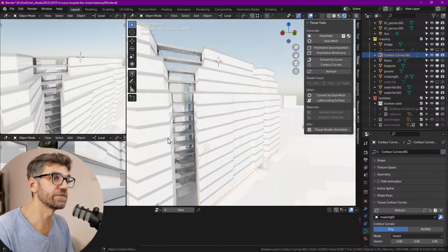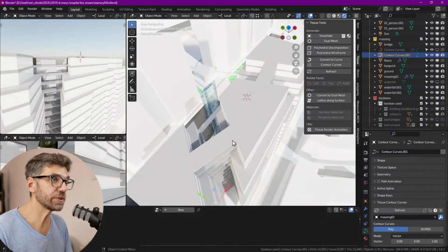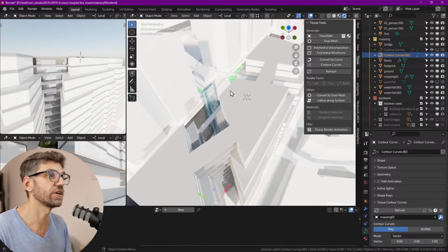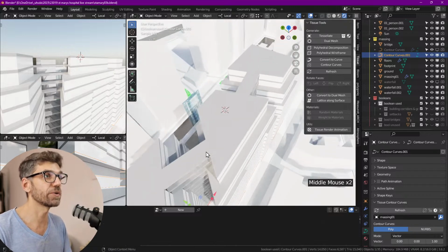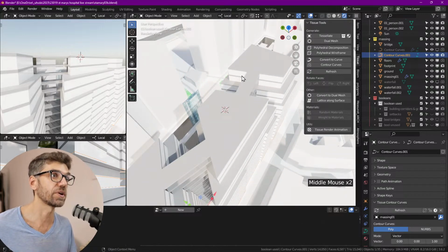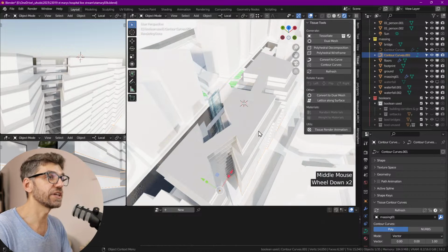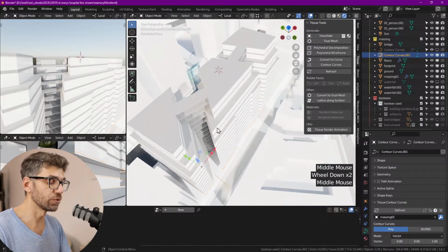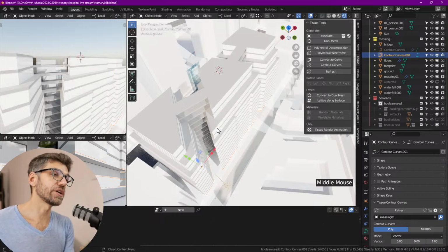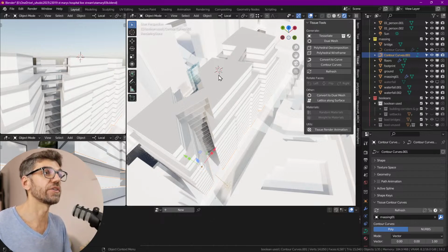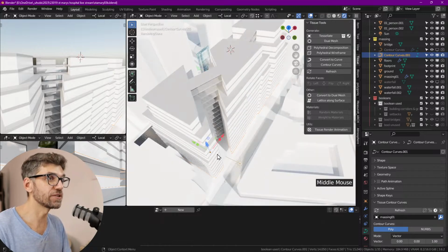Now, why do we need the bridges in the first place? So we've got 3 buildings, but those 3 buildings should really function like one building, meaning that most of our circulation is here. The main vertical circulation, lift cores, they all happen in this central building. In these corner buildings over here, we're going to have just emergency circulation, secondary ones, and maybe some service lifts or emergency lifts and stairs, right? But everything has to happen through here. So we don't want to have too many circulation cores, right? So we don't want to have another lift core here and then another one here and another one there. But this way, even though it looks like 3 massings, it is functioning like one building with our bridges. That's why they're so important.